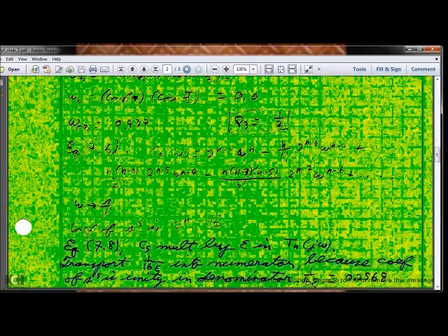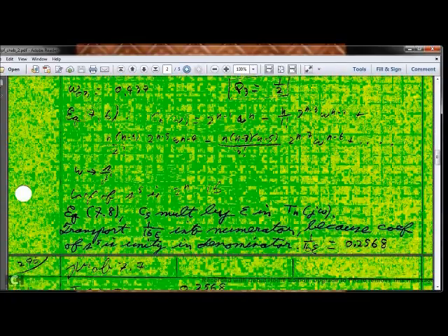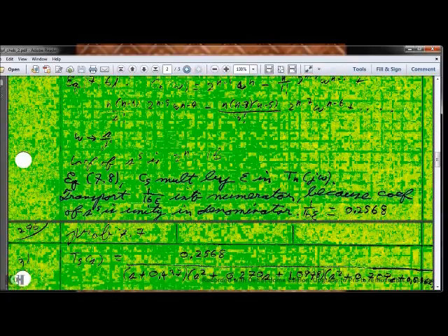Unfortunately, the expression of the Chebyshev polynomial did not come through very well. We make the variable transformation from omega to s over j. We find the coefficient of s to the 5th is 2 to the n minus 1, or 16. So what will be the magnitude in our numerator? Well, it's going to be 1 over 16 epsilon, because we are normalizing to get s to the 5th in the numerator.